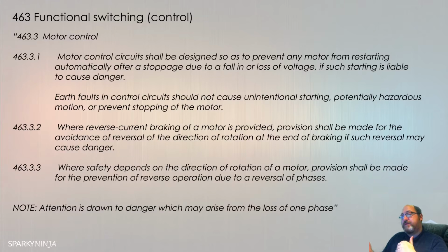If we lose one phase in a three-phase motor, it will kill all of the phases, and if that phase was to then return, it won't just automatically restart if the restarting of this equipment is likely to cause any danger. So what it's saying is, if you do have functional switching on a motor, it will not be automatic unless it's been considered that that is a safe consideration, a safe assessment.